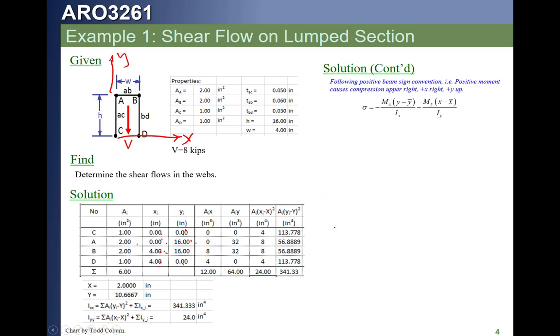Actually, we can do it directly in this table. Mx over its I minus My over its I, and the y minus y bar and x minus x bar give us the total stress. In this case, we only have an Mx, and since we're going to use a unit moment, it doesn't matter how long this beam is. We're just going to take that V times 1 is our unit moment. If that's our stress, our force in any cap will be that stress times the area. So we can calculate the change in force like this.